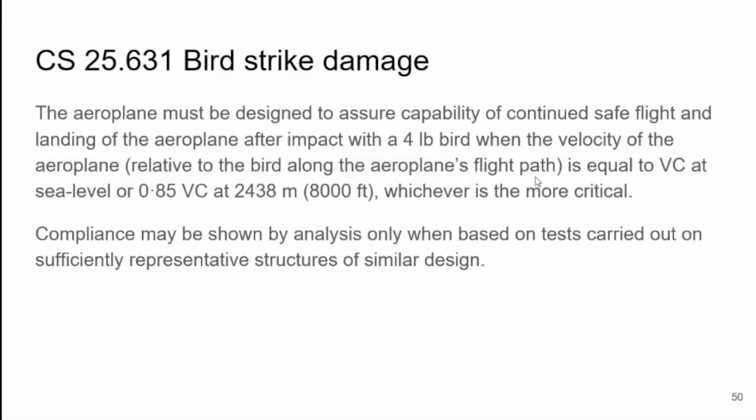Bird strike is also something very significant. They shoot the bird. We need to get a 4 pound bird to satisfy the requirement, and they treat this the same as metallic. They shoot the bird also, but again we go back to the problem of the composite, because of the hidden damage, it may have the impact and the damage may not be seen. But for the 4 pound birds, I think it can easily damage the structure. I've seen the radome punctured through by these birds.